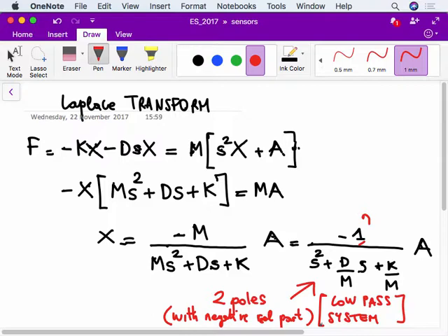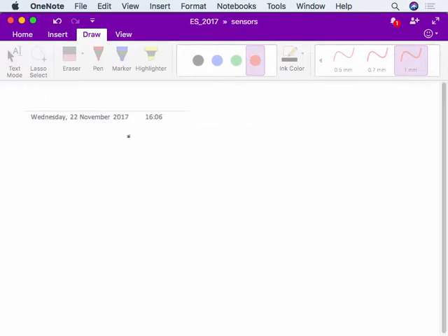So this is the main part, and once we have this, everything becomes much simpler, because now the displacement must be transformed into a change of capacitance, and this is relatively easy, because if we use this displacement to modify the distance between two plates of a capacitor, we change with the displacement also the capacitance. Okay? So let me write this concept.